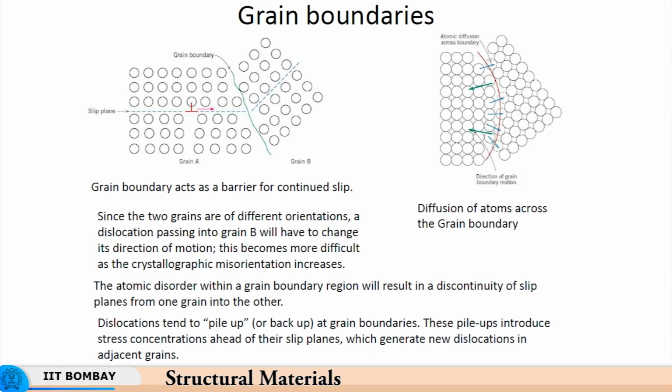They have been interacting with each other, with the interstitials, and with the grain boundaries. They get held up at the grain boundaries, and therefore they are unable to cross over the grain boundary, impeding the movement of further dislocations. So essentially, due to various interactions between a surface defect like a grain boundary and a dislocation, and a point defect like interstitials and a dislocation, the impedance to the movement increases, and therefore the forces required to move the dislocations continue to increase.